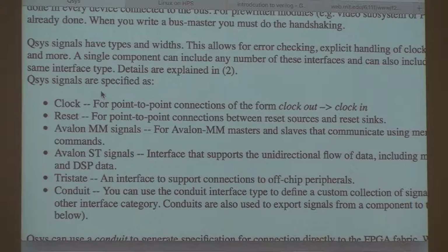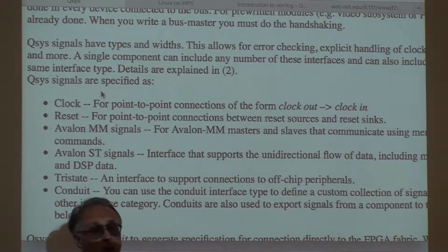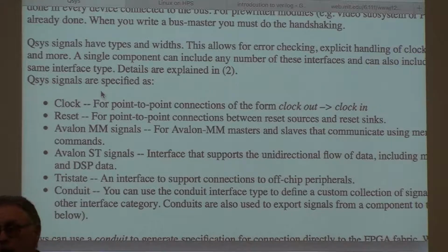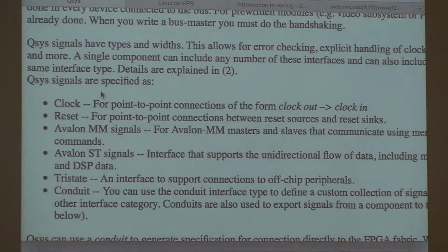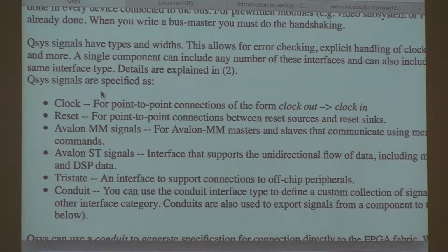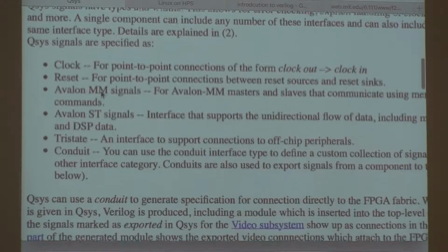So when you specify a conduit export, you're allowing those signals to be exposed onto the Verilog interface to your Qsys. And you'll be doing a lot of that. And I'll talk more about that.